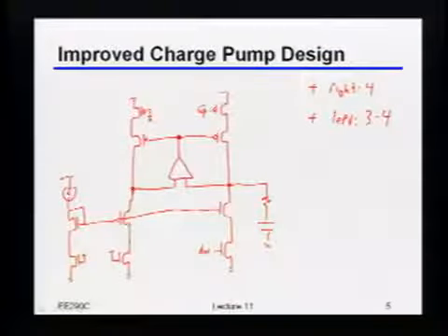Because remember, there's a PLL here. So can you arbitrarily move this voltage around, given that there's a PLL feedback loop? Or no? You can't, right? Ideally speaking, the PLL makes the impedance of that node 0, right? Because that voltage has to be whatever it is to get the frequency right, okay?